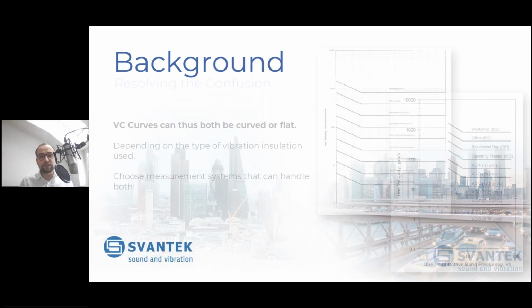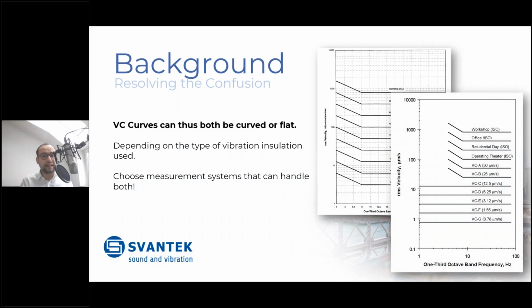Now remember again, I'm going to show this here. For example, the VCA curve, that is something that goes from 4 to 8 Hertz when it comes to that curve, and then it operates flat all the way to 80 Hertz. Now, if you will have a scenario where there is a pneumatic insulation on the flooring, then you might want to think of making it flat all the way to 1 Hertz to ensure that through this you have not introduced another vibration level in the low frequency field where you were not expecting anything.